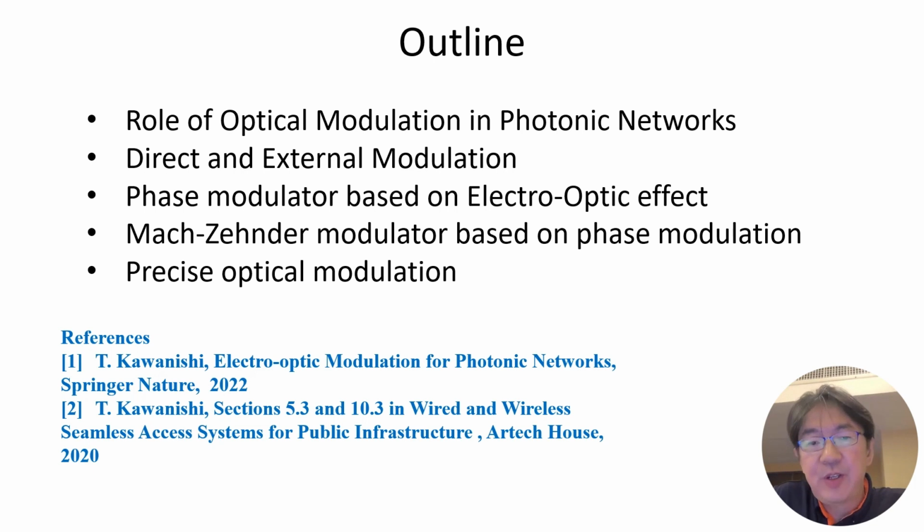In this presentation, I focused on EO effect, electro-optic effect modulators, because they can offer high-speed modulation and precise modulation. The EO effect induces the optical phase shift.